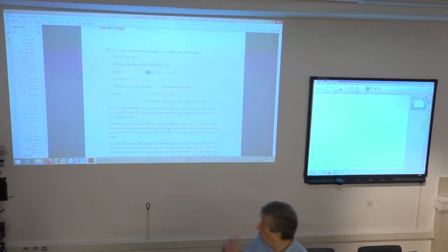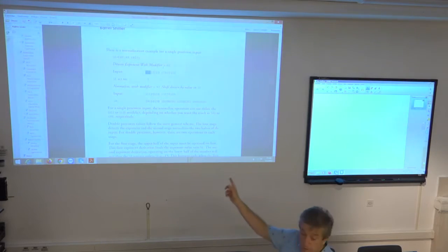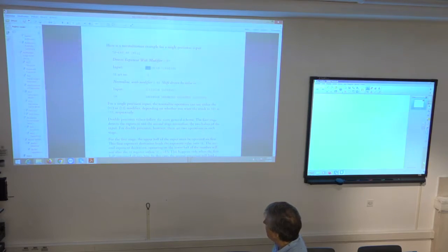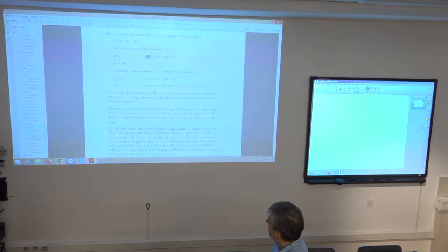So if I use the norm instruction after this one, it will simply take this -3 value, convert it to +3, and then perform a shift by 3 positions to the left, and you will have normalization of the input value in two assembly instructions. Okay? And then it describes the application of this high and low reference to perform double precision